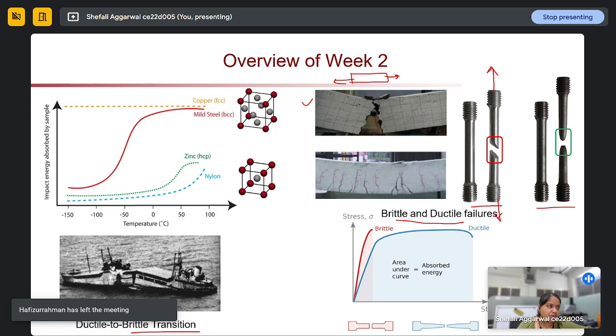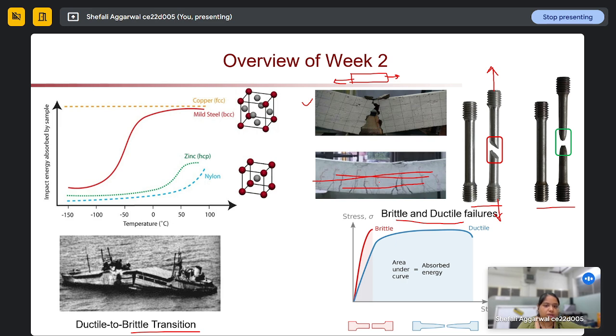So this concrete will have rebars inside it. Rebars are put in for tensile strength. So what will happen? The failure won't be a brittle failure. First cracks will initiate, different cracks will be there, and then those cracks will propagate. So that will be a ductile failure. If you see the stress strain curve, in ductile behavior the area under the curve will be very high, whereas in brittle behavior the area under the curve will be very low.